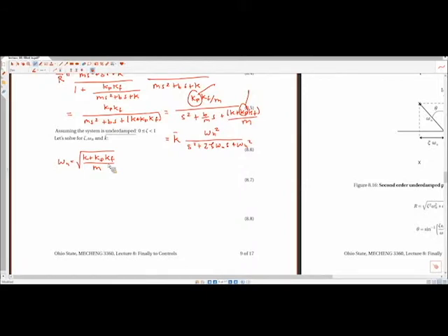Well, you can have an overdamped system that's in the left half plane. It just so happens we're injecting energy into the system by having a feedback loop, because we have some sort of controller that's often amplifying the error signal to create the input, and so in a certain sense we're injecting energy into the system.